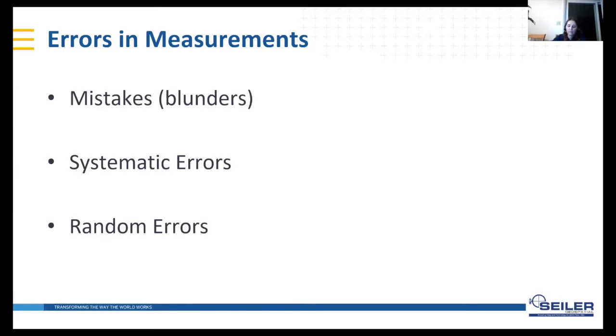The network adjustment is actually the same as traverse adjustment, but this is a never-ending process. You can apply the network adjustment for hours and hours and days, constantly changing the results step by step.